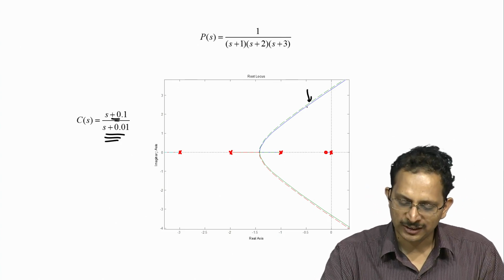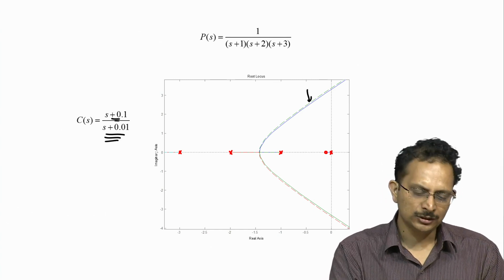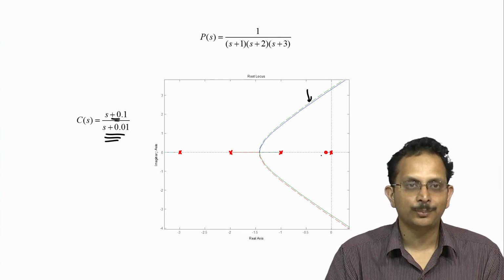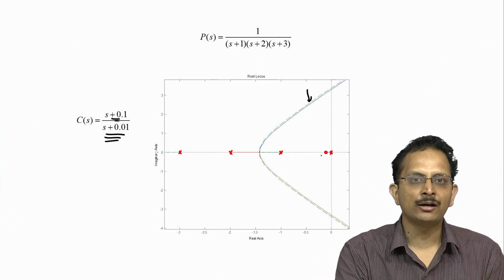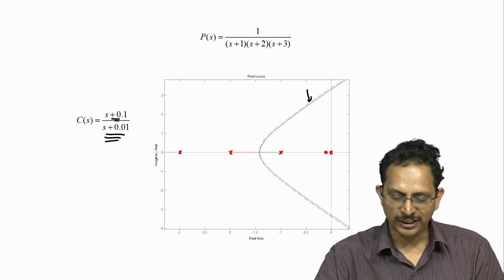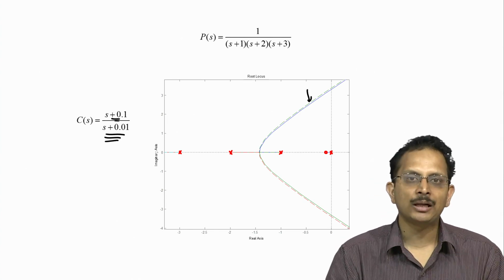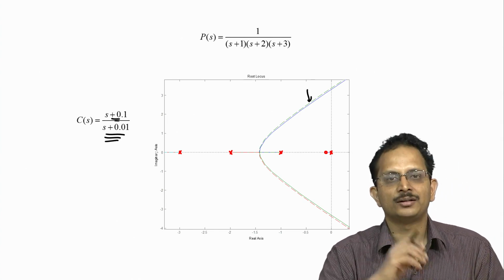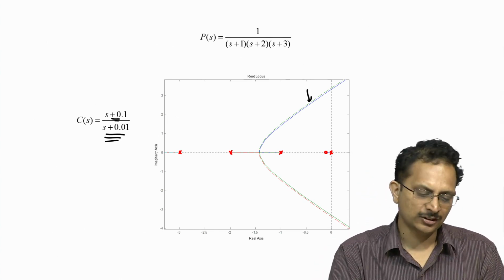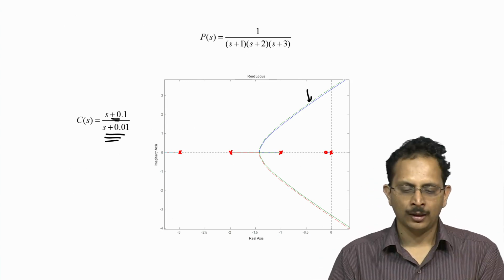And what you see is that these two curves are very close to one another, which indicates that this particular controller allows us to improve low frequency performance by adding a gain of 10 in the low frequency region, but without significantly changing the dominant dynamics that we might have already designed for this particular system. And if one notices, this controller structure is essentially that of a lag compensator.